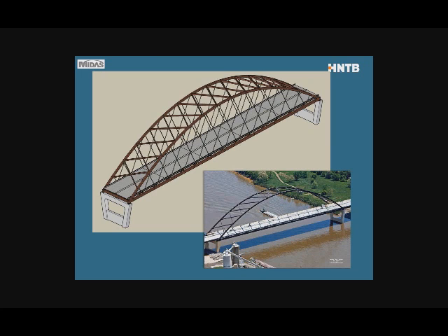We like it as an alternative to truss systems. That behavior I've described earlier, the great stiffness, is characteristic of truss structures. But unlike truss structures, we also have the redundancy that we can afford the loss of a few of these hanger elements, which with a truss you could not.